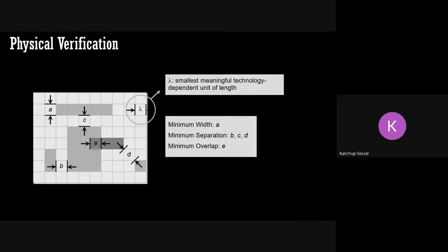If there is a question, if any of these fails, which team will deal with this? In the chip design flow, there are multiple steps. Let's say RTL design: an RTL person is designing RTL, and there will be a verification team which is verifying it. Place and route will do the place and route, while static timing analysis will verify that. Typically there is no single point of failure in the chip. Whatever you do, it's checked double or triple by multiple tools in the flow.